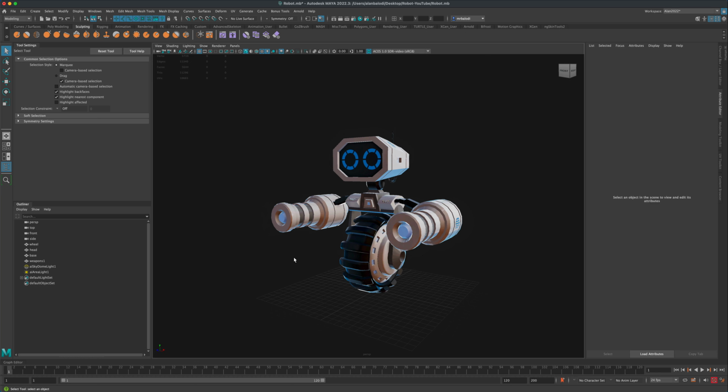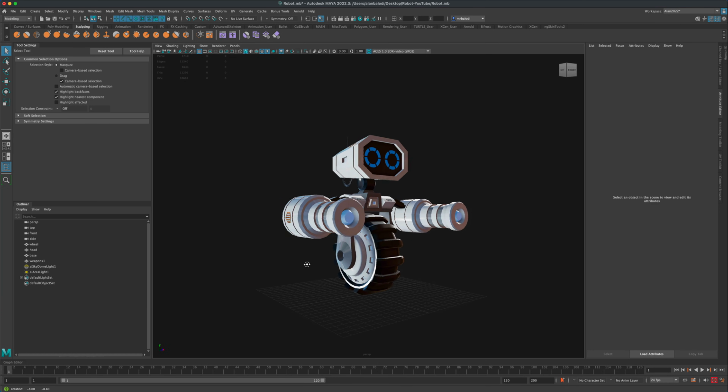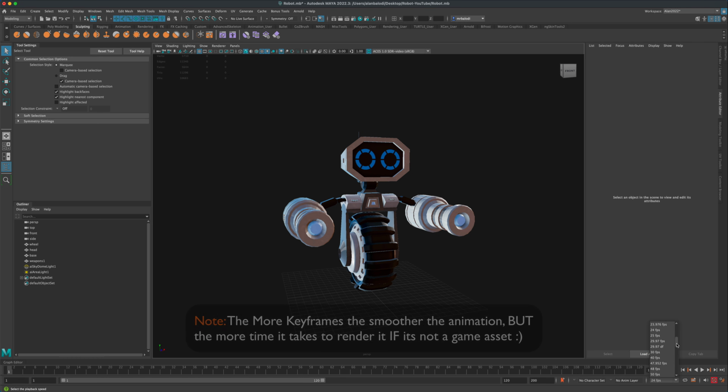So for example, if you are creating something really simple and maybe you're just creating a short animation here in Maya and you have no reason to get too crazy, one of the things we could do is maybe first decide how many frames per second you want your animation to be. So in my case, it's currently set to 24. If you're doing this for a game engine, a lot of times the requirement would be 60 frames per second. So you just have to figure out what it is you're doing and what it is being used for.